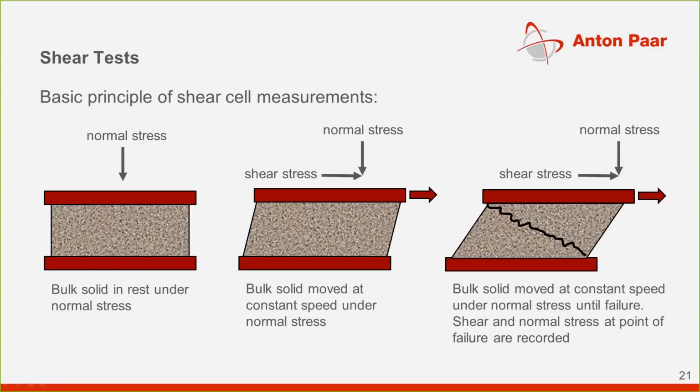Okay, so with that finished on the shear tests, oh yeah, right. There are actually a few different ways of shear testing. The first way that exists and that was done in the beginning was translational, which meant that every shear point or failure point had to be set up separately. In the meantime, which is quite common, is to use either an annular ring or just a circle, which makes it a bit easier and faster to run these tests, or quite a lot faster actually.